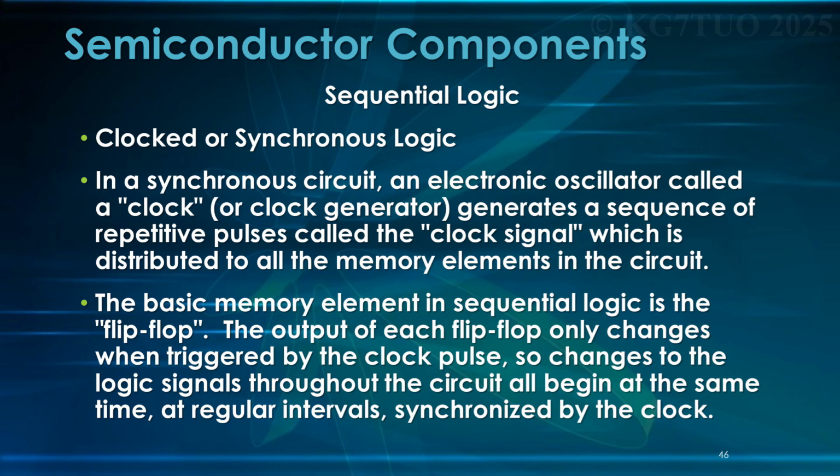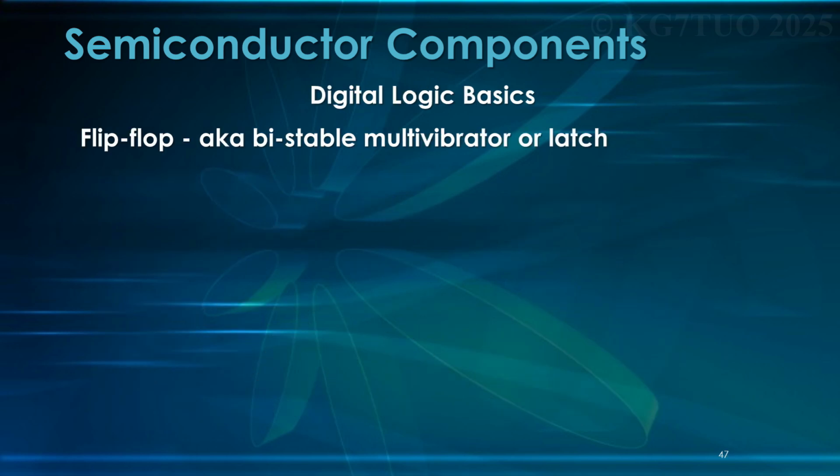The basic memory element in sequential logic is the flip-flop. The output of each flip-flop only changes when triggered by the clock pulse. So changes to the logic signals throughout the circuit all begin at the same time at regular intervals, synchronized by the clock. Flip-flop. Yes, Leo. A bistable multivibrator, or latch.